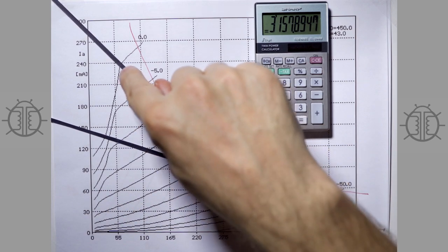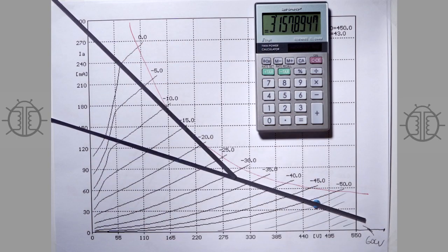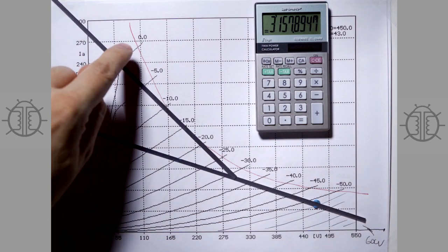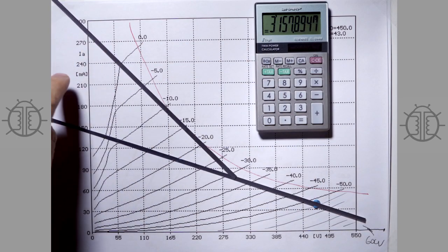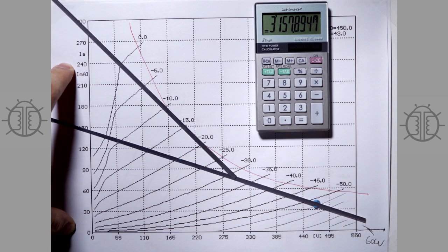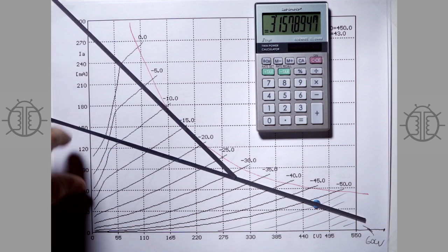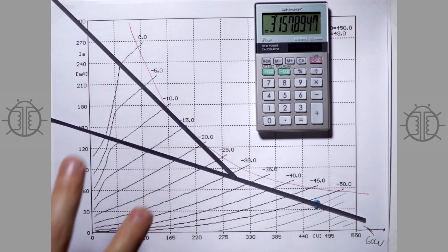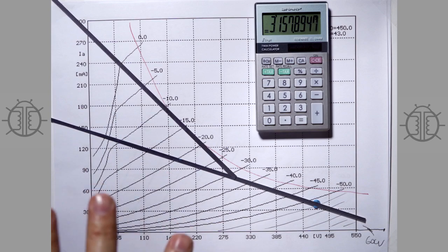Now look, we're swinging way, way, way more current because we have access to this area now. We're swinging up to like 240 milliamps, and we're swinging down to cutoff basically. So we're swinging 240 milliamps. You remember with our class A single-ended stage, I think we were swinging 80 or something like that. So you can already see, and we've got 2 tubes now instead of 1. And so you can see how much power is now available with ultralinear versus triode.